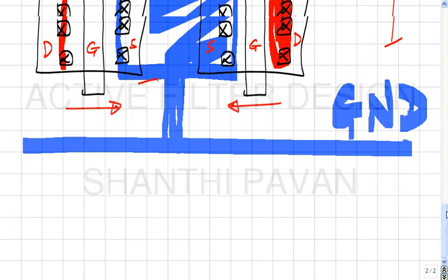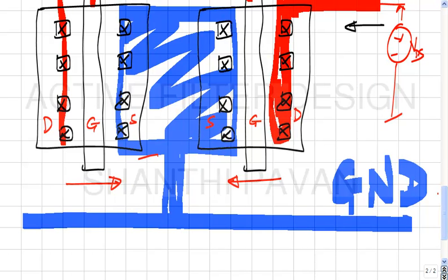All right. So we just discussed that these two transistors are not identical. One, because current doesn't flow in the same direction in both the devices, and two, because of this ion implantation process, the way ions are implanted, the shadowing and so on. Therefore the two transistors are technically not identical, though on the schematic you draw them as two identical devices.